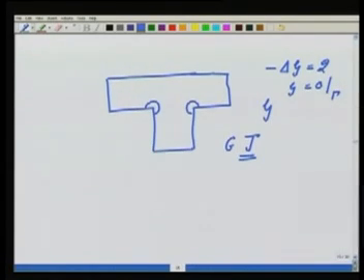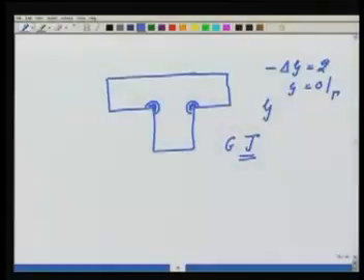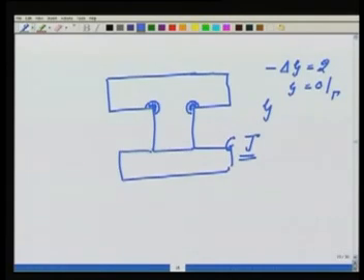Solve this problem and we are done, from where we can get the J. You see here again there is a singularity in the vicinity of these corners for one of the very popular domains that we have, and this can be handled by doing mesh refinement in the vicinity of this. Another section we are interested in is the I section. Again same problem. Here again we will have these corners and so on. So now we have a tool with which we can solve all these problems for polygonal domains.